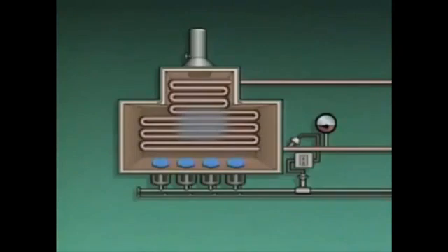If air in the furnace reacts with the unburned fuel building up in the furnace, the fuel may ignite away from the burners. This ignition may produce a positive pressure in the firebox. The positive pressure further impedes airflow into the furnace, making the original airflow problem even worse. This could cause even more unburned fuel to accumulate in the furnace.